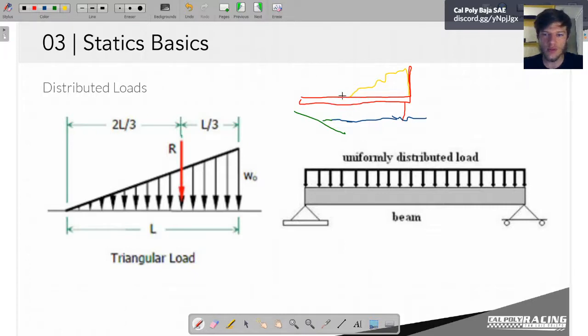And the weight of this sand is going to even itself out to where it'll look like a triangle there. I'll draw that again in black. So the sand will just shape like a triangle. Now you know that the weight of something, obviously over here where there's more sand, is going to weigh a lot more than down at the end here where there's just like, I don't know, 4 or 5 grains. So we represent that with a distributed load.